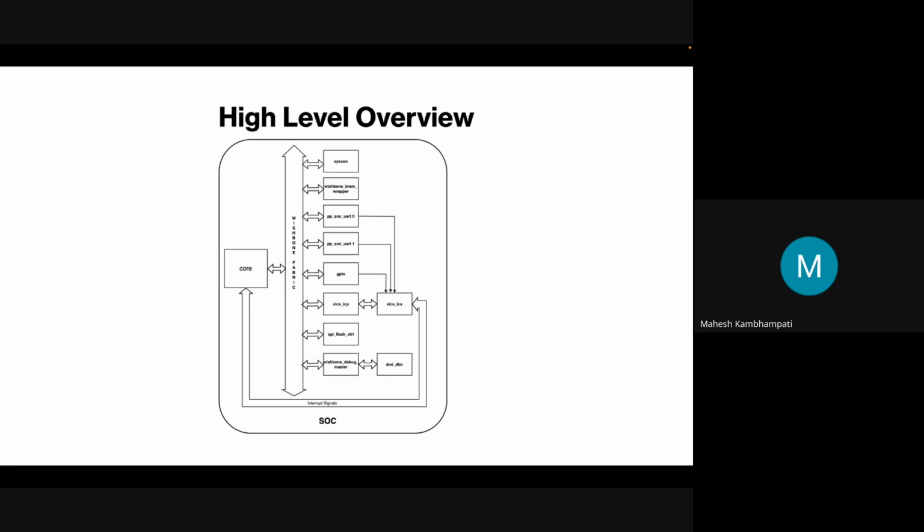So I have done a block diagram of my basic high level understanding. We can see multiple components here. We see the big brain, which is the core, and there is also the system controller and Wishbone DRAM wrapper, which is necessarily a BRAM or block RAM. And we see these peripherals, two UART blocks and GPIO. And then these are the XICS, ICP and ICS, which act as a pair, necessarily IBM's interrupt controller system, which helps in communicating with the peripherals.